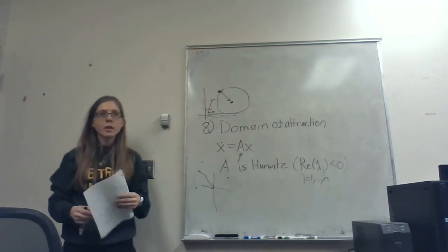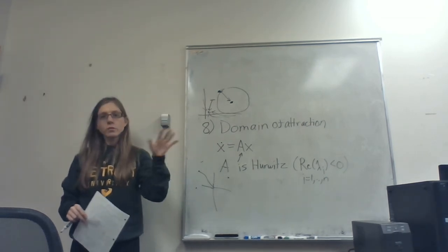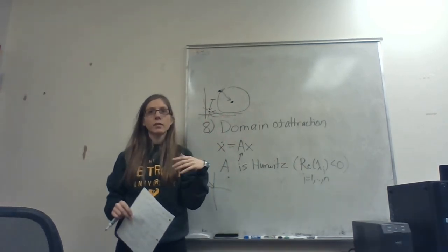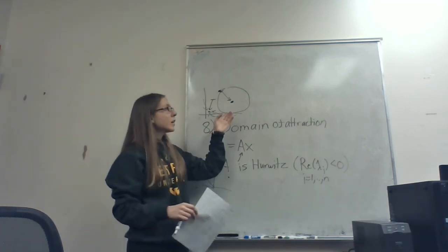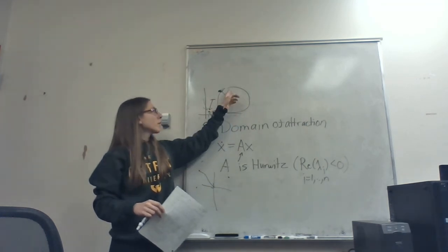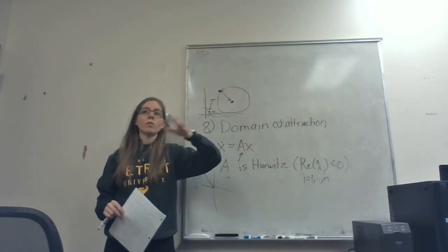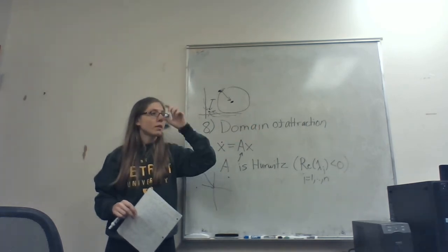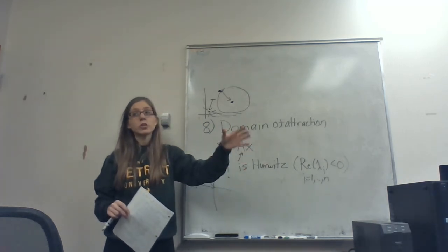That's really important in control and systems theory. For the moment, consider no control. In that case, it's essentially like you're applying the steady state input, maybe off your steady state. So it's open loop. Is it open loop stable or open loop unstable? You apply the steady state input so that your equation is no longer a function of the input, it just has the steady state built in there. The closed loop state will only go to your actual steady state that you're trying to drive it to for a certain range of initial conditions in most cases.